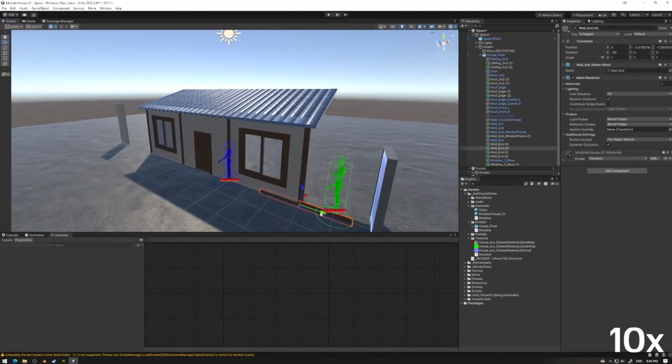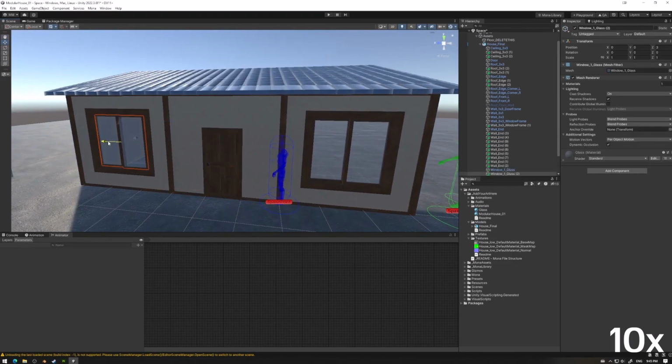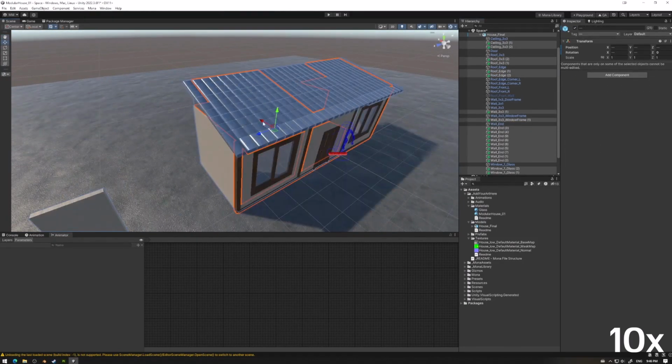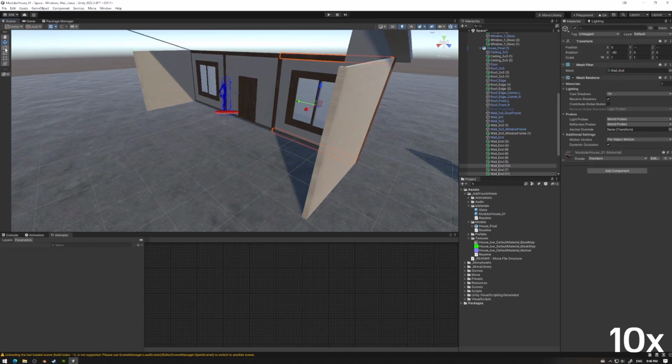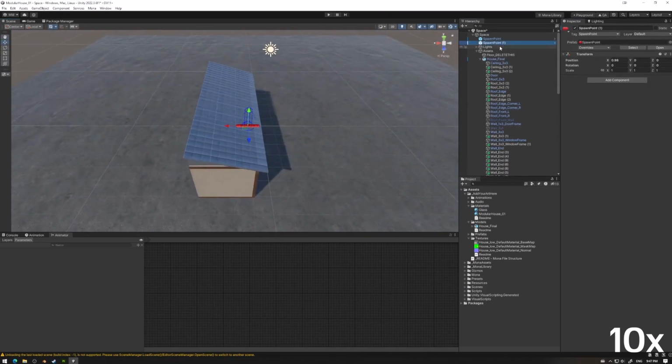As you can see, setting up the space is super quick, as I've made all the assets accurate lengths to the default snapping length in Unity. The snapping length is 0.25 meters by default, so it's highly recommended to make your asset as a derivative of 0.25. As these walls are 3 by 3 meters, it's very easy to line them up.